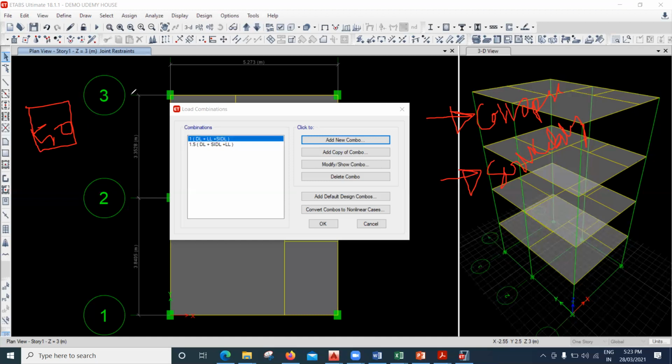So I'll multiply this by 1.5, that is 50 into 1.5. How much does it come out to be? It comes out to be 75 kg, right? So whenever I design this slab, I'll design it for 75 kg. Let the load coming be 50 only, but I'll be designing this for 75 kg keeping the future point of view, right? So this is called limit state of collapse.